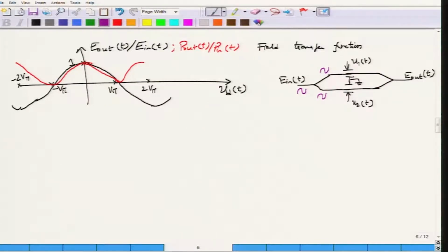So, if they are in phase, while this is rising, this will also rise, while this is falling, this will also fall. So, essentially the electric fields at these two arms are in phase with each other. As they propagate, this one will undergo some phase shift. Let us say this is my reference electric field, then after phase modulation, this is my phase shifted version.